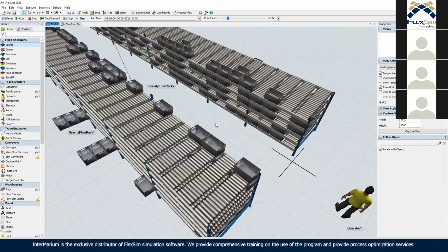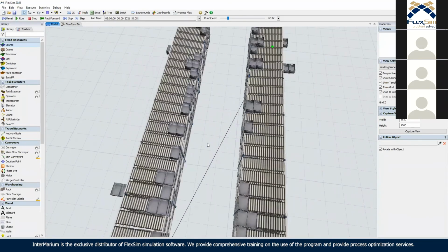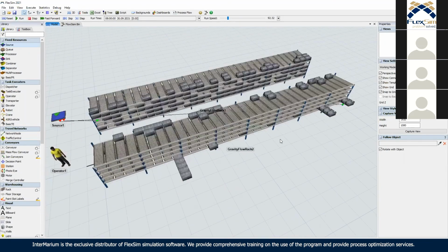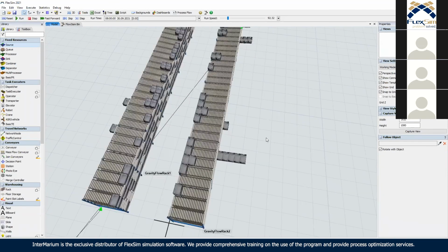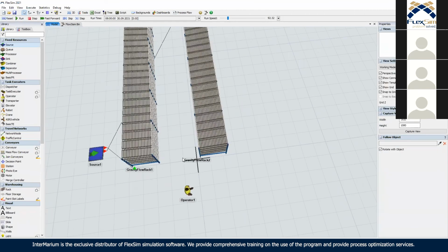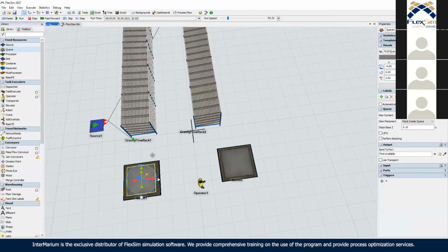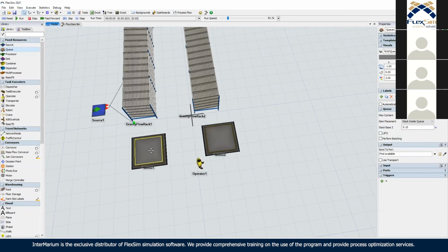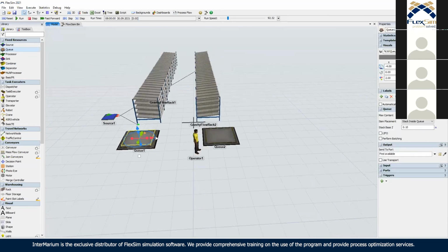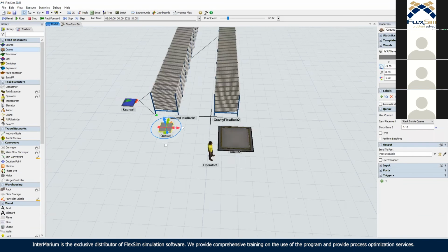Okay, we have the very basic supermarket right now. As I said, we won't go very deep into the logic of the placement or the taking of the KLT, but we want to have a supermarket, and I want to fill the carts, the trailers, with the product. So our next step is to create 2 buffers for this operator. The first buffer, I will change its shape, maybe this box, 0.1, and we're going to name it empty carts or trailers.